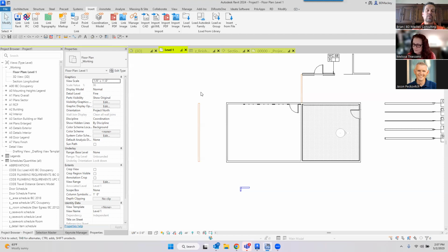I did play with it just to see once that I brought a file that I did not upgrade to the current version of the BIM 360 project. I just dragged and dropped it up there from Windows Explorer to my browser page, and then I could actually link in an old Revit file. So it was like a Revit 2018 file I can see in 2024 without having to go through the process of upgrading it. So I haven't got into it yet, haven't used it on a real project. It does work. It seems to be working pretty well.